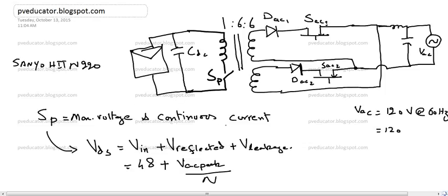And then the last one is this V leakage. This V leakage corresponds to the voltage due to the leakage spike of the transformer leakage and magnetizing inductance. According to some application notes by Microchip Technology, this V leakage is nominally from 30 to 35 volt under the full load condition.